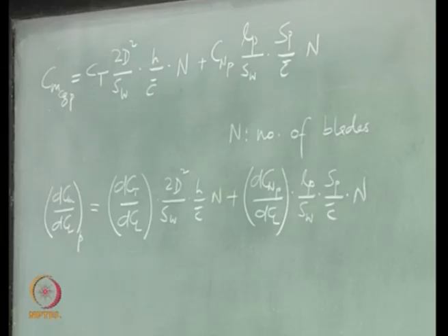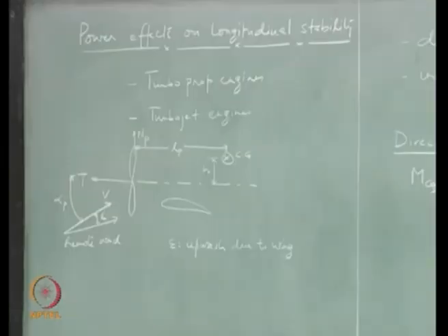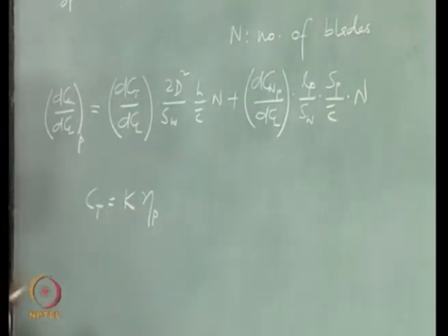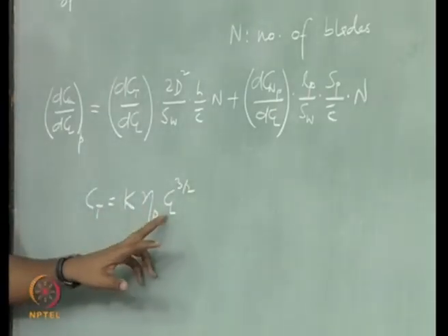Yes or no? CL is the lift coefficient of the aircraft, right, and that will depend upon the angle of attack at the fuselage reference line, right, and the thrust produced is also going to depend upon this angle, because you are seeing the flow at some angle, isn't it? So this CT is a function of propeller efficiency and the lift coefficient of the aircraft.